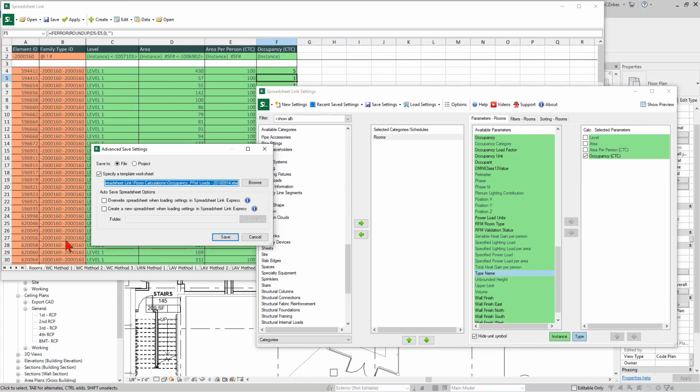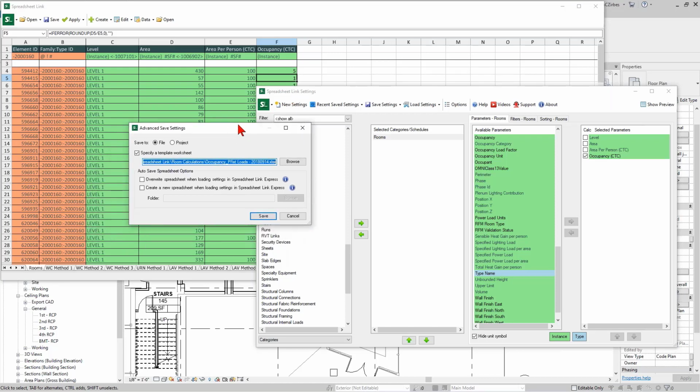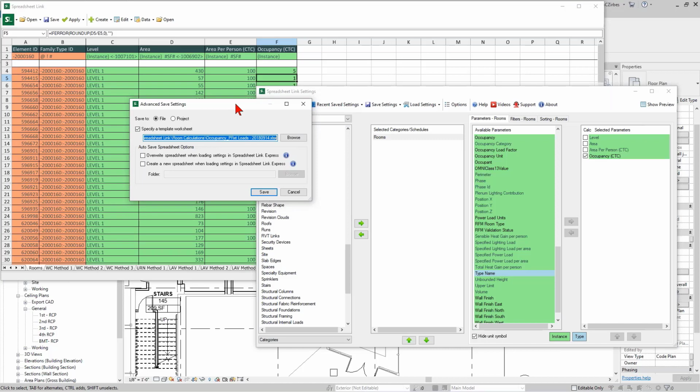But now, because I have these other tabs out here from Excel, Excel can know to look up off of a rooms tab that already pre-exists, that's now populated with my project's data and has my calculations. Really powerful when you start to dig in to that level. You only have to set it up once, and once you have this set up, every team member on your team can now load those settings and have it automatically run your calcs.